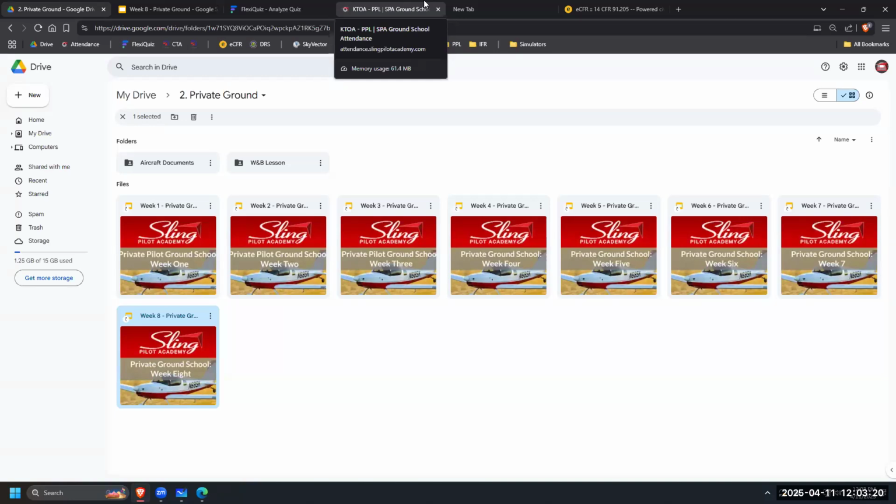You said you're gonna do two. So, you agree? The other one is spiraling slipstream. All right. Corkscrew effect. As the propeller spins, it creates airflow around the fuselage, hitting the left side of the vertical stabilizer, causing the aircraft to yaw to the left.